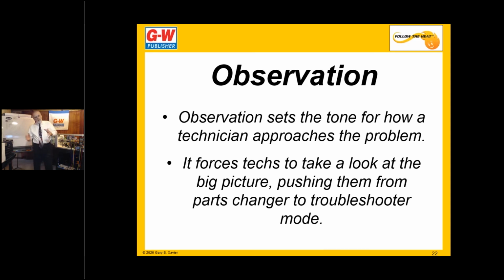As I walked in, the chilled water pump was not on. I had two in parallel, one was running, one was not. And so I immediately started to take the housing off the pump. And then I realized, well, before I do that, I should probably shut off the power. So I walked over to the panel and the breaker was thrown.